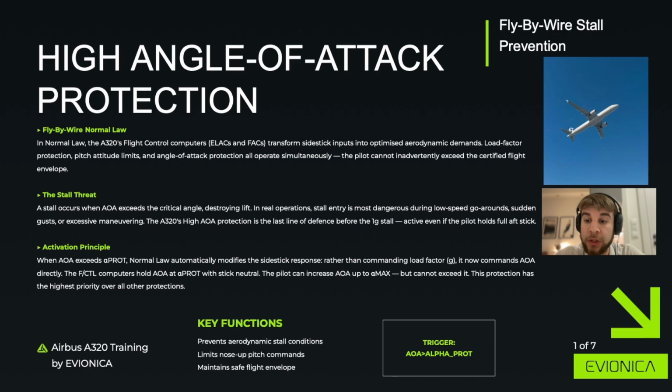A stall occurs when the angle of attack exceeds a critical value, causing a rapid loss of lift. This can happen during low-speed operations such as go-arounds or during excessive maneuvering. To prevent this, the A320 includes high angle of attack protection, which acts as the final barrier before a stall.